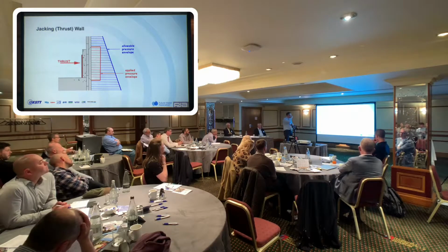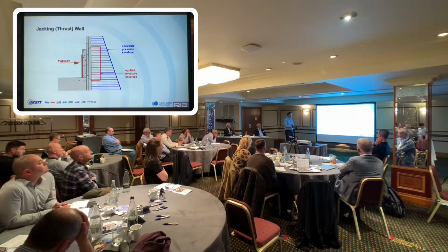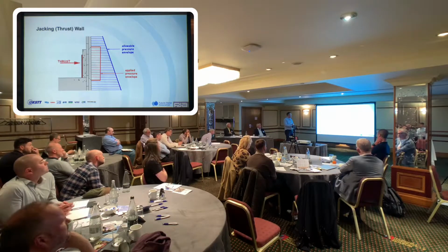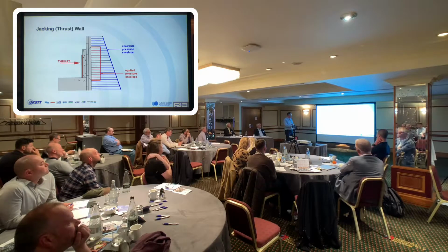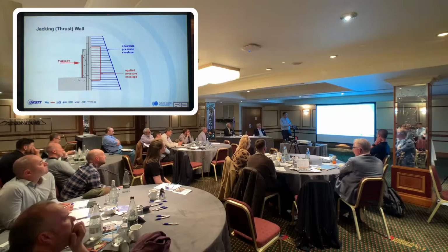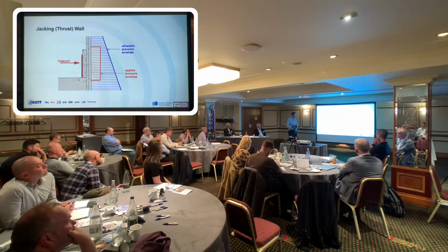So just in terms of how the thing works, in all those scenarios, the back wall is exactly the same, and what that develops, whether it be up on the column or just through the localised section itself. So you work out an applied pressure envelope, in its simplest form, as you would do for an embedded retaining wall, a sheet piled wall, or a shaft.